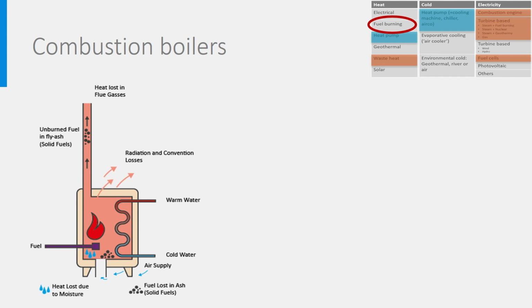This heat exchanger will bring heat to the heating system of the building. There is a fan above expelling the fumes and combustion products like CO2 and CO to the outside through a pipe. As you may remind, these exhaust gases may have a temperature up to 150 degrees Celsius. This setup is known as being a non-condensing boiler.